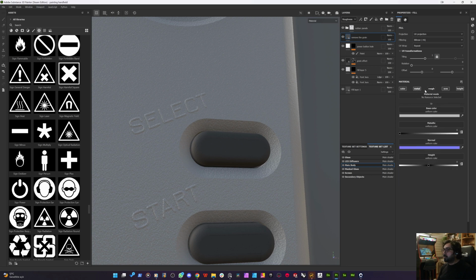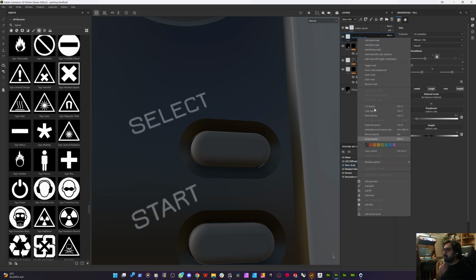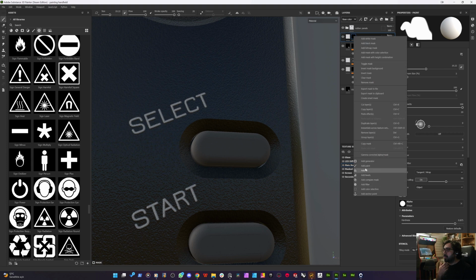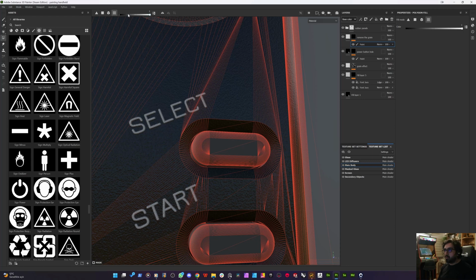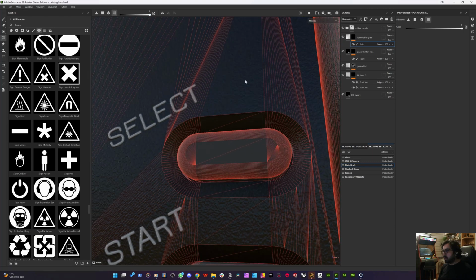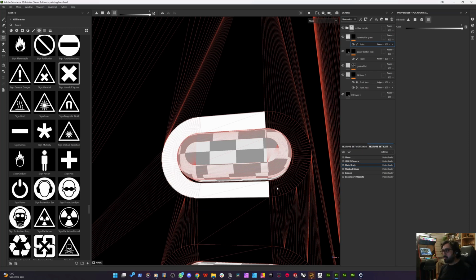From certain areas. So for that, I'm just defining a height and roughness channel. Since we have given the noise or the grain look by the height channel, I'm setting this height's blending type as normal on this layer. And next I will add a mask and add a paint layer to define some areas to be not affected by the grain, like these parts.